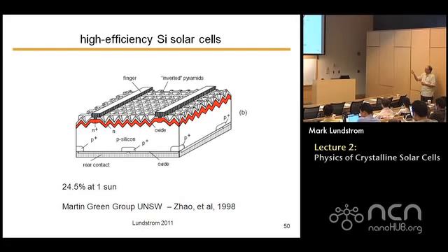But all I need is an ohmic contact to that P-type layer, so I could take that heavily doped region and make it a very small area, just little points, and make contact just in those small areas. Any electrons that get to those small areas will recombine, but the total area is a small fraction of the area of the back surface. I'm inserting a silicon dioxide layer there, which will passivate the back oxide, tie up all the dangling bonds and give me a low back surface recombination velocity.